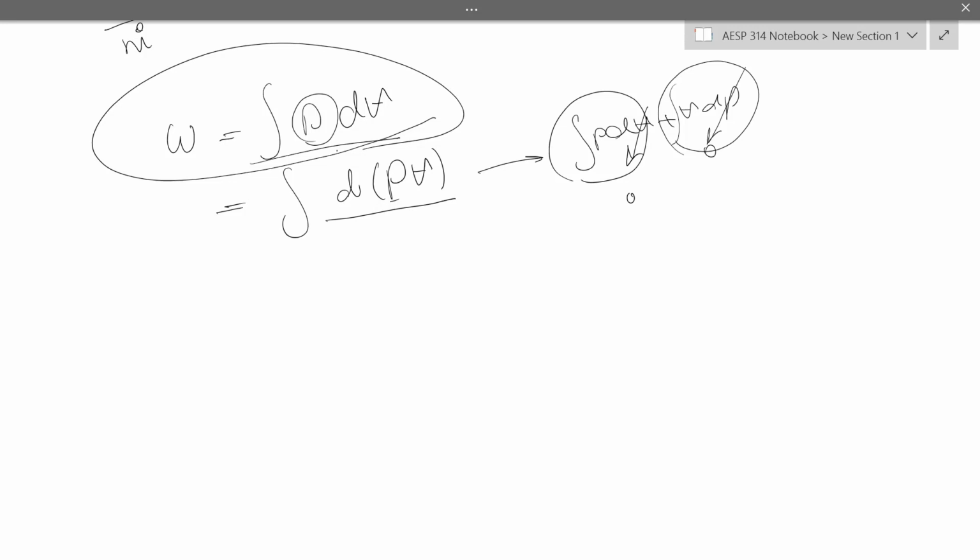Can we use this to our benefit at all? Think about it. Is the volume going to change here? We are pumping water. No. What about pressure? Pressure is going to change. So the equation we are actually going to use is the integral of V dP.